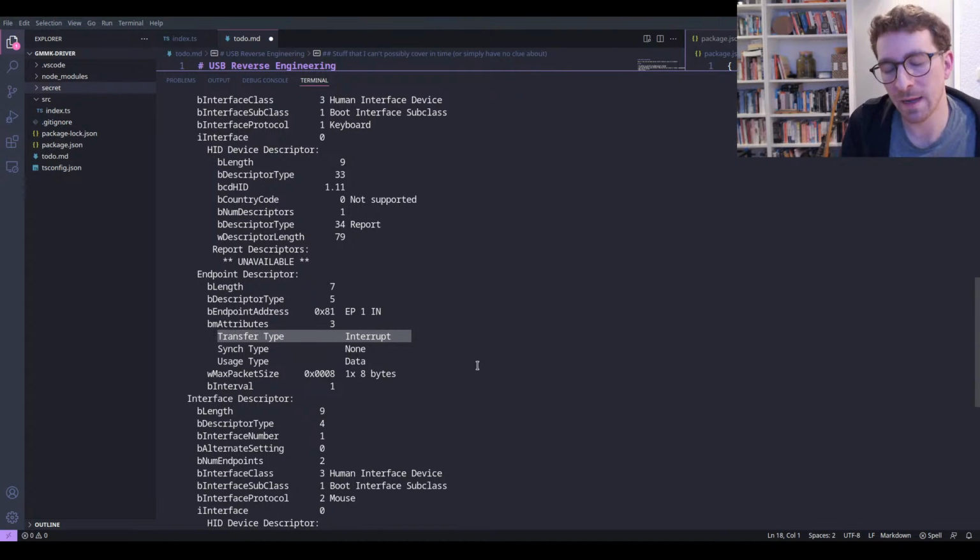The confusing thing is that if you've ever used microcontrollers or done low level programming for operating systems, then you'll know that interrupts are things that you don't control. They come into the system and you have to deal with them when they happen. That is not the case in USB. In USB, the host computer initiates everything.